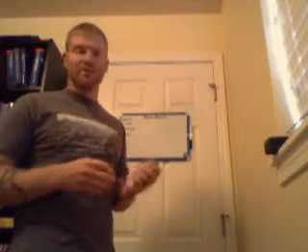Weight and balance is one of those things that's really important to calculate each time you fly. Basically, flying outside of the center of gravity limitations, flying above the maximum gross weight, or below the minimum gross weight, these are all things that can lead to a really hazardous situation.